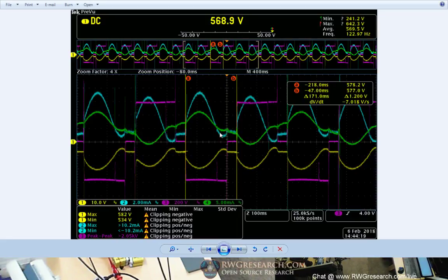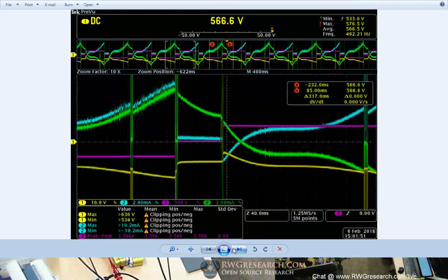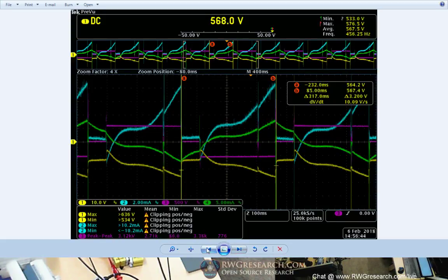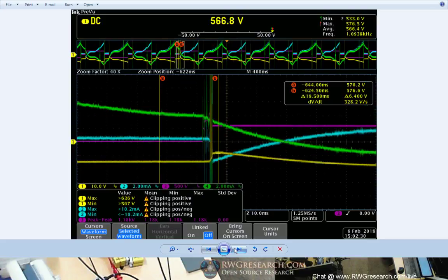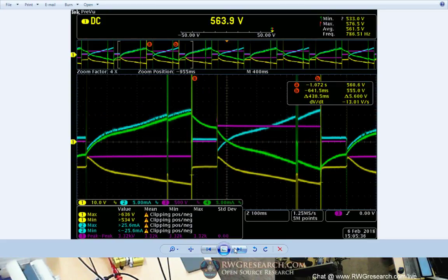With that said, we'll go to a different screenshot here, and I'll show you the negative current for people who don't know what we're talking about. Let's start right here. Here we have shorted the coil, and it's got some energy left in it. When that energy gets here, this is energy left and induction all at the same time, and we get this very large negative current spike, and then it goes way up. This is a gap between two pieces of copper on the commutator. Then we keep charging, and then we do the reverse.